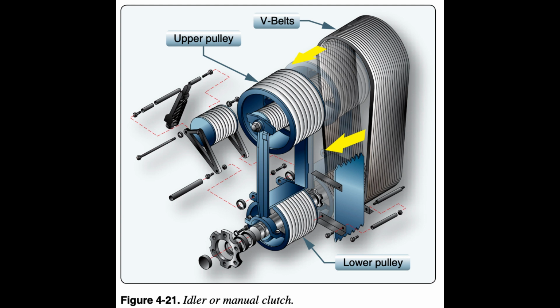Once the engine is running, tension on the belts is gradually increased. When the rotor and engine tachometer needles are superimposed, the rotor and the engine are synchronized, and the clutch is then fully engaged. Advantages of this system include vibration isolation and simple maintenance. When the clutch is not engaged, engines are very easy to overspeed, resulting in costly inspections and maintenance. Power, or throttle control, is very important in this phase of engine operation. Centrifugal clutch.